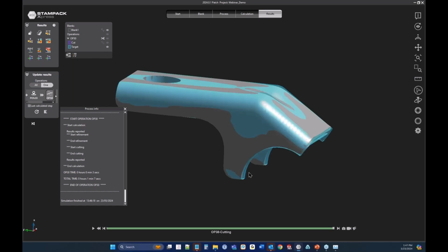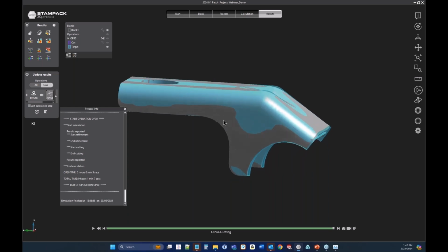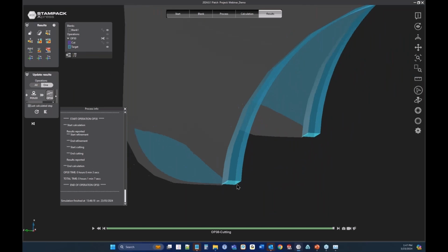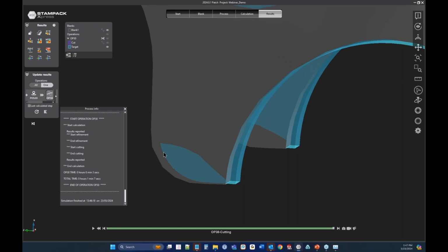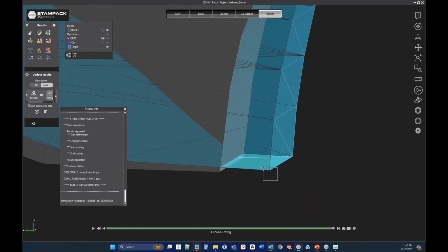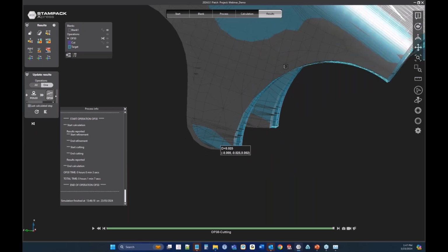So the next thing we can do is we can take a look at our target geometry compared to, in gray, what our simulated geometry is. And already you can tell that we have quite a bit of issues. The physical geometry that's getting formed by simulation is kicking back towards the back end of this quite a bit. And if we want to know exactly how much, we can actually just go into our measure command here. And you can do this at any point in your simulation, measure between any components. But here we see that this is 25 thousandths. And if you recall, this file had 10 thousandths as its limit for its tolerance. So right now, this part is out of tolerance.